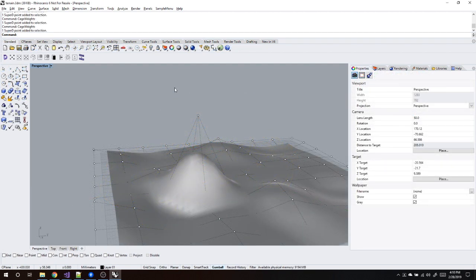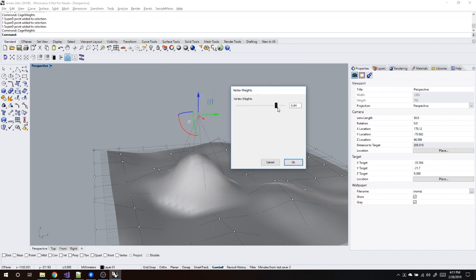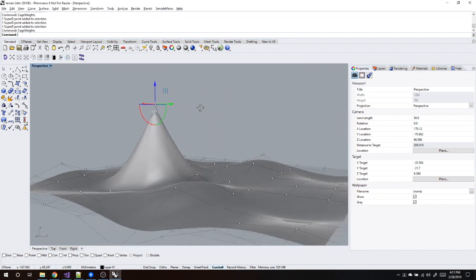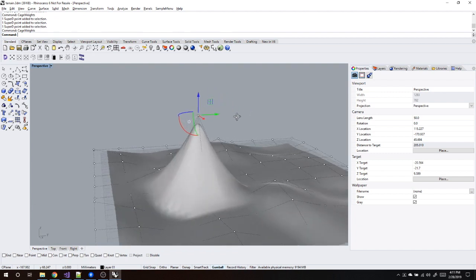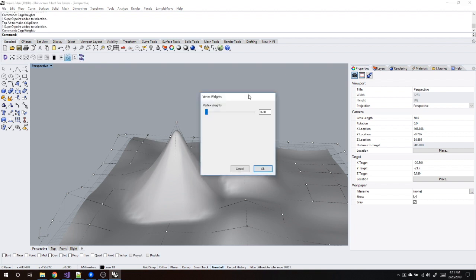In addition to changing the global fullness factor, every SuperD control point has a weight value, which will affect how much the surface gravitates towards that control point. Shown here is an example of what happens when a weight is drastically increased for a given control point. When neighboring values are set for vertex weights, an average of the two closest vertex weights will be used to compute the final result.